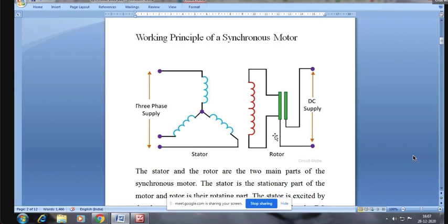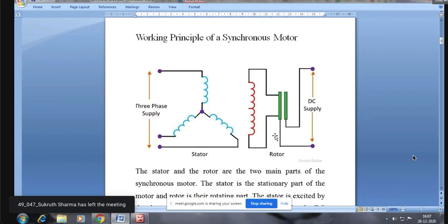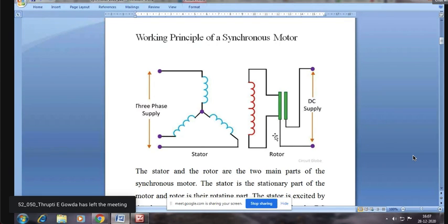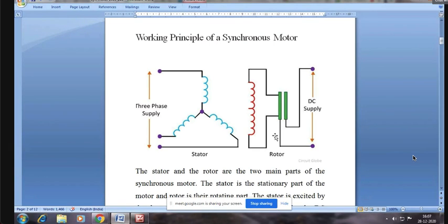Rotor flux. No, no. Armature is not rotor. What is armature in an alternator? Stator, sir. Stator. Correct. Armature doesn't rotate in an alternator. Even in case of a synchronous motor also, it will not rotate. Therefore, in a synchronous machine, in general, the meaning of armature is stator. So we have stator flux, that is armature flux, and main field flux. Correct? Similarly, in this synchronous motor also we have two fluxes, stator flux and rotor flux.